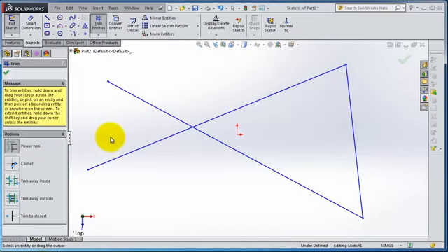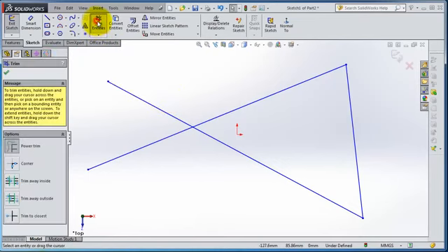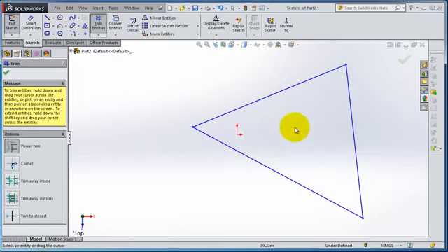So to use the power trim, just keep clicking on the left mouse and make a line. So you are trimming, and again holding the left mouse button, move, then you are trimming. Control C. Let's activate trim. We have power trim. You can also trim both of them at once by clicking or drawing that trimming line.